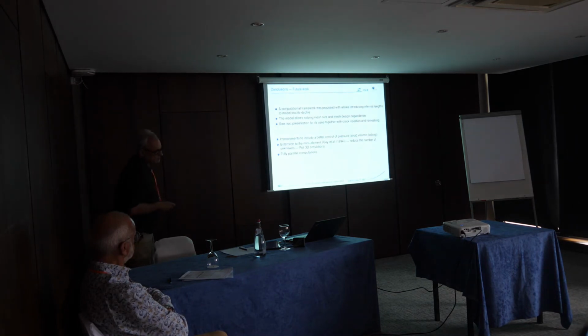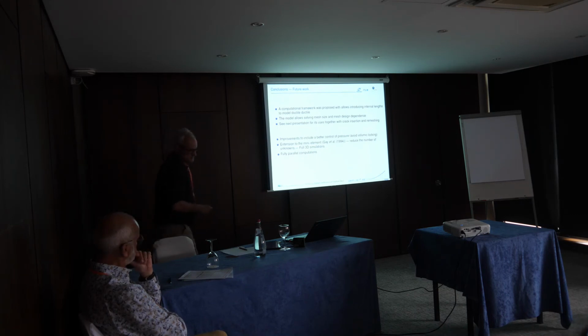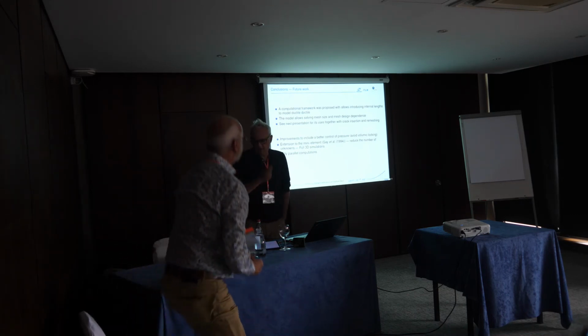So some conclusions, which I'm going to skip very fast. We have the computational framework. The model indeed allows to get rid of mesh dependence. And the use of this model for cracking and crack insertion and remeshing will be presented in the next talk. Improvements will include better control of pressure to avoid volumetric locking, which occurs sometimes, and improving the elements using linear interpolation for the displacement to go really into 3D simulation, and indeed doing fully parallel computation. Thank you very much. It was slightly too long, sorry.